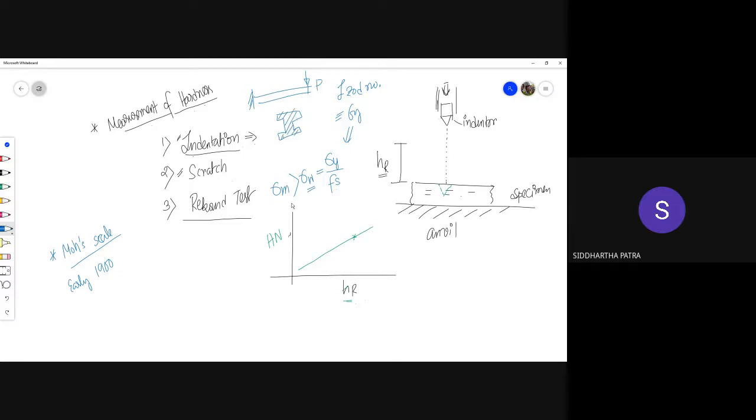Then I can choose the dimensions so that the maximum stress in my system is smaller than this working stress, which is yield stress divided by factor of safety, and I can choose that factor of safety to be somewhere around 3, let's say.